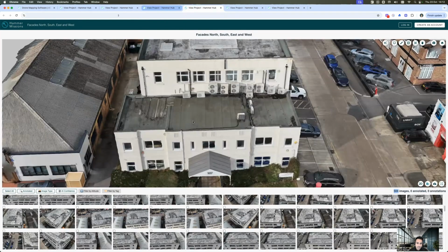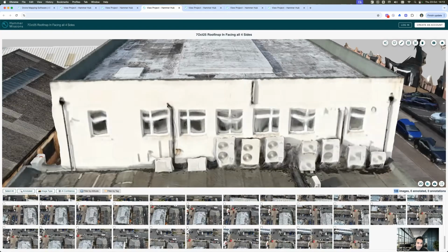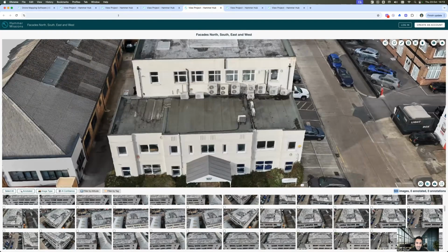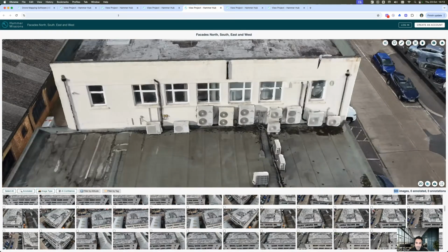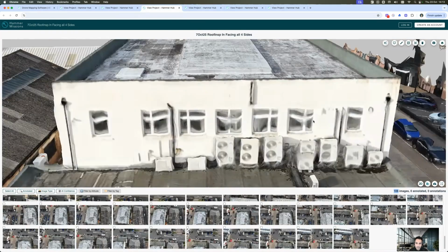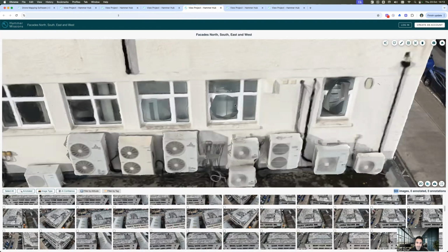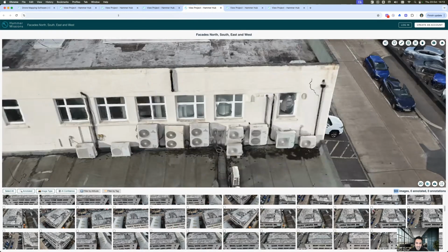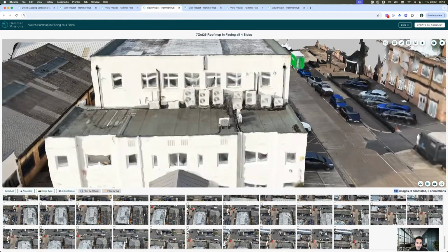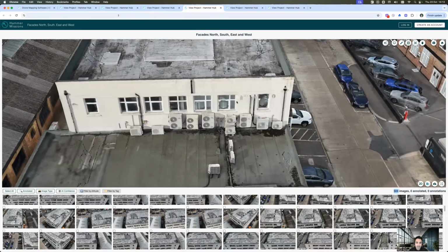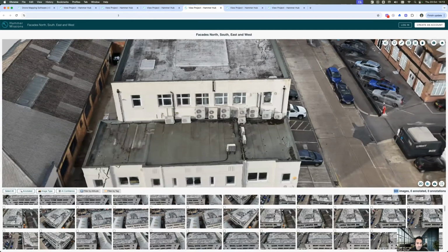If you look at these windows, let's go into these windows a little bit. These are all sort of wobbly and a bit washed out, and everything looks a bit gooey. Whereas if we go to our facade mapping, everything is now more rigid. Everything looks like a window, and you're able to pick up on all these other details which typically won't be available. So, for example, there is some structure here on the exterior wall of the facade. It's visible on this particular flight plan and this particular result, whereas it's not even visible on this other structure. So, very, very important to keep in mind that the facade flight plan actually adds a lot of detail to your 3D model.